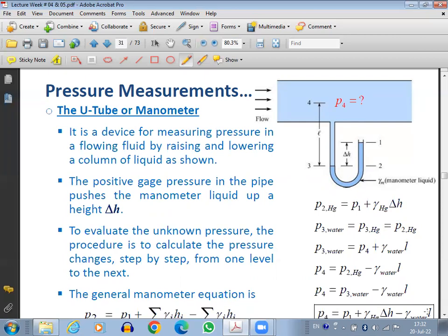वो जो disadvantage था that we can only use it for liquid, cannot be used for the gas. Now U-tube manometer eliminated it. Why? Because now we have a pipe, but I connect this pipe in the form of a U shape, and within this U-shaped pipe, I put another liquid in it. So even if air is flowing through it, the air is going to come here, will push the manometer fluid, but will not come out. So it's trapped inside. So it eliminated that issue.